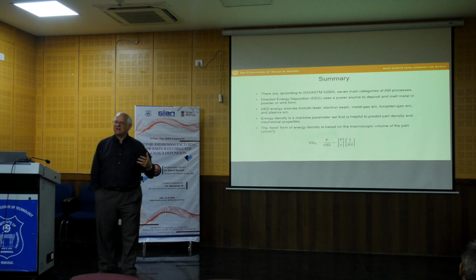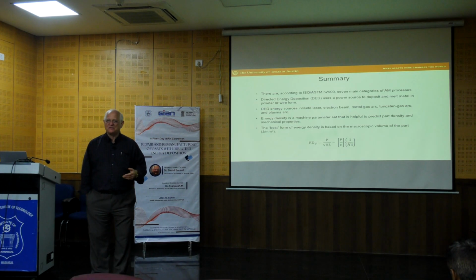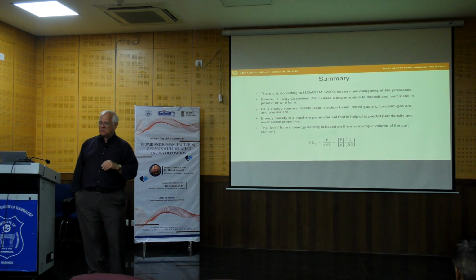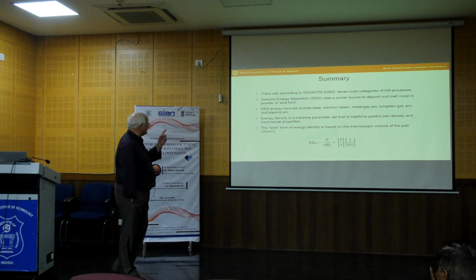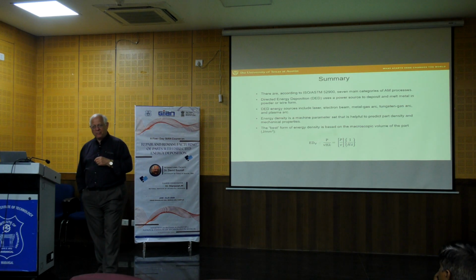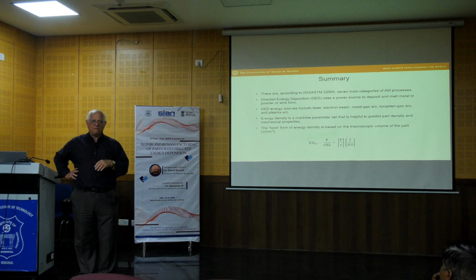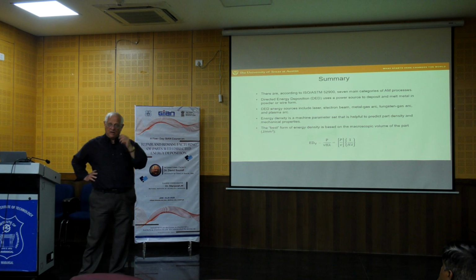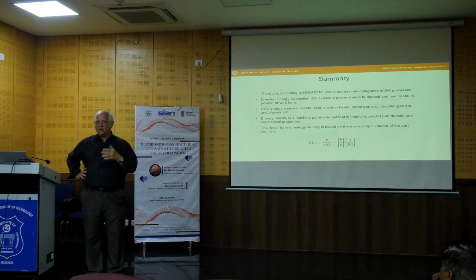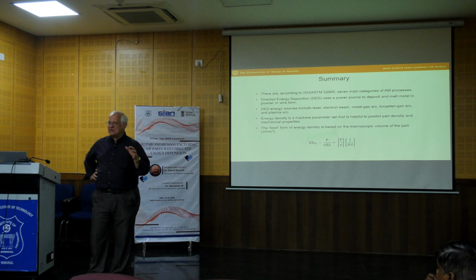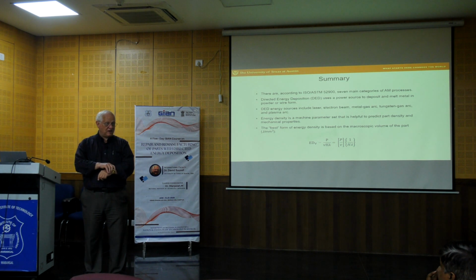I consider this lecture to be sort of the preliminaries for DED. So in the next lecture I'll talk about mechanical properties in DED. We're going to be completely, wholly immersed in directed energy deposition at that stage. Anyway, it's important to note that there are 7 major categories of additive manufacturing process, according to ISO/ASTM 52900, and we've listed those. I said earlier today that all of them were developed around 1987 to 2001, and everything since then has been sort of a variation on the theme.